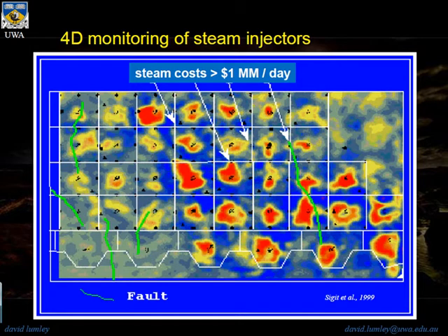You can see very nicely in all these patterns where the steam is going, a lot of information in here. You can see the flanks are not taking steam so well. You can see nice patterns where steam is spreading out circularly. You're going to get a high recovery factor for that pattern. You can see other ones like these two, which are breaking through north-south, and as soon as they break through to the producer, you've essentially got a short circuit there, and you're going to leave behind 80% of the oil.